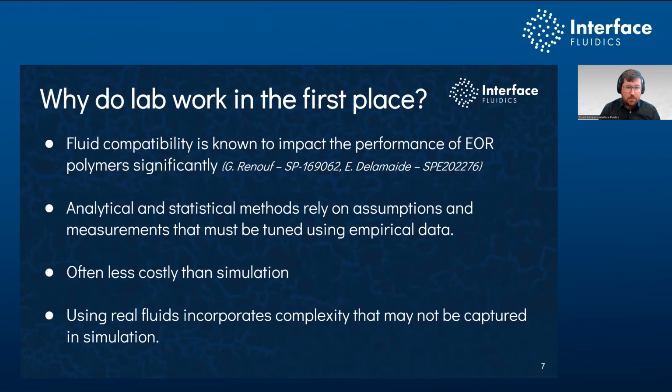First of all, fluid compatibility is known to impact the performance of enhanced oil recovery polymers very significantly. There's extensive literature. I've cited a few papers there, but understanding how water and chemistry interact is the number one way to optimize a polymer flood or other enhanced oil recovery project. Chemistry that gains viscosity typically is highly dependent on the composition of that water. And so finding good water sources and understanding those water sources really does impact your performance.